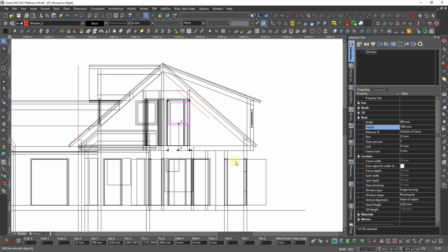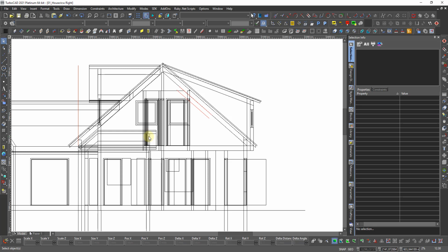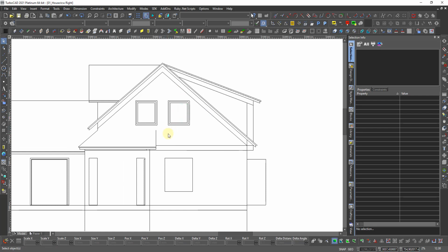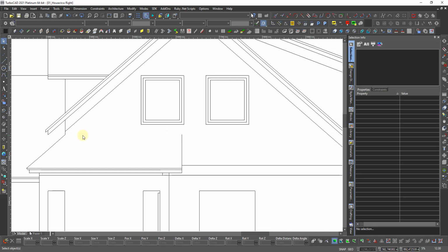So that means there's 900 millimeter from the top floor up to the window. That means also it's legal. So we leave it like that, I think. And I go to hit 9. Yeah, and it also now does not crash, you see here.